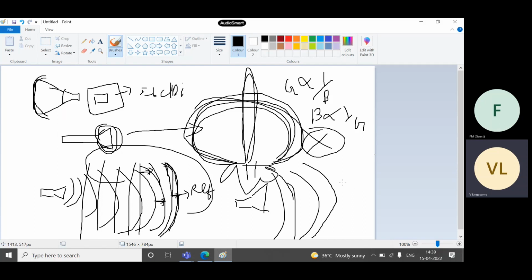The planar waves are achieved in the far field distance. We used to say that, right, more than 2D square lambda. If you keep it there, then you will approximately receive the planar waves. So why do we require planar waves?